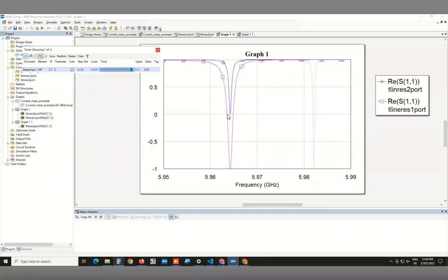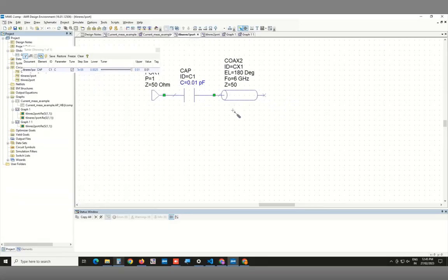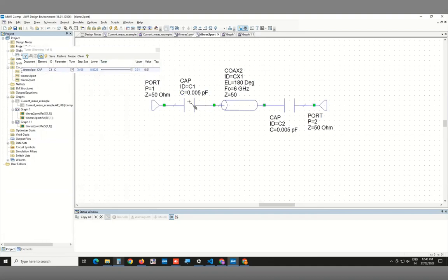Because now, if I look again at the midpoints, this is the width here, whereas the width for this guy is still smaller. And that's essentially related to the fact that the Q factor changes, I think, as the square of the capacitance, whereas the frequency changes linearly. So even though in order to shift this resonator frequency to the same as this resonator's frequency, because 5 femtofarad, 5 femtofarad, total capacitance is 10. So that's why it exactly matched at 10 femtofarads.